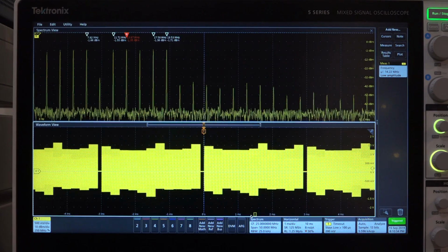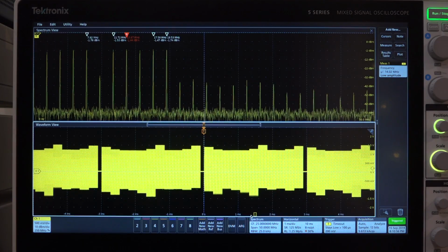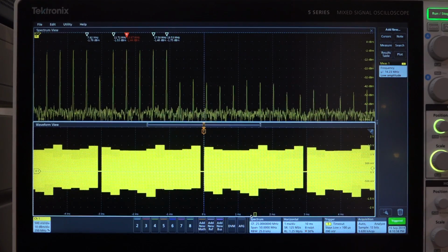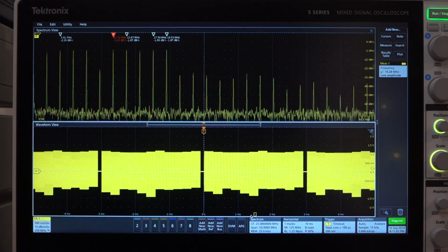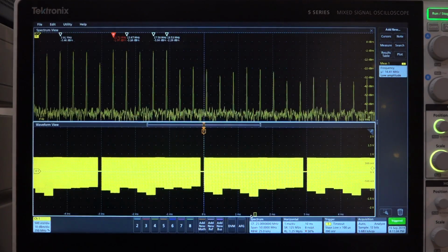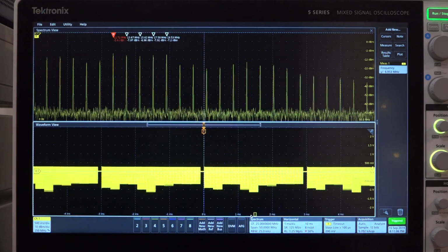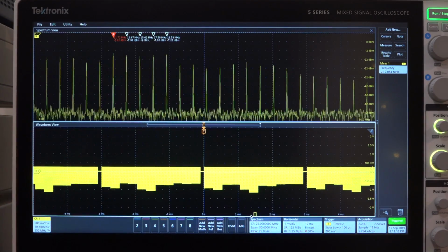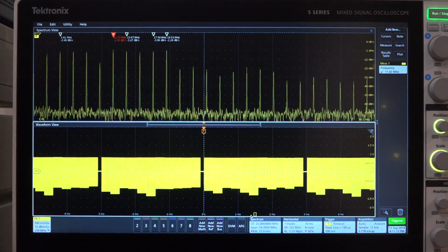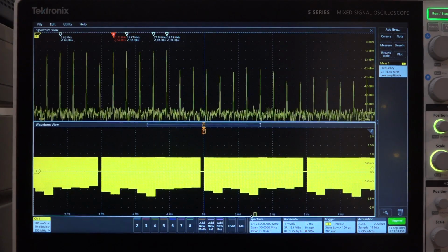If you look very carefully, you can see that the output power of the amplifier is not changing, but we are getting significantly more nonlinear. Eventually, we're going to reach a point where the output power is also going to start going down. There it is. You can see everything going. Now the missing tone test is completely gone. You can see the amplifier is totally saturated on one end. So let me go back up and show you a couple of other interesting features.